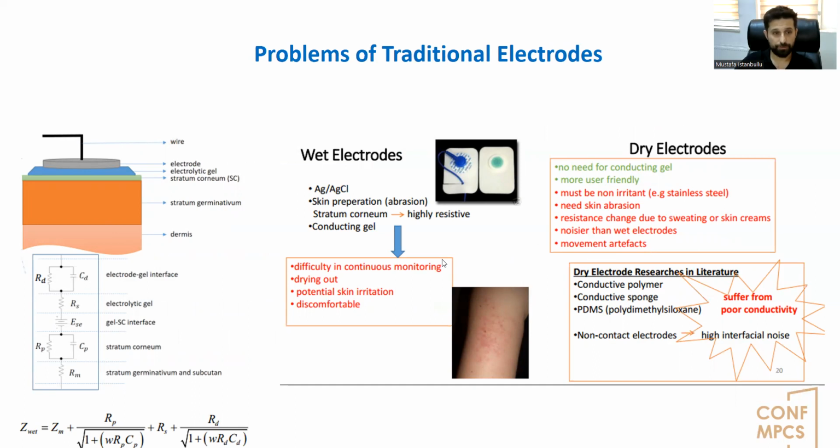In addition to the electrophysiological signals, there are also undesired signals due to noise, artifacts, and interference, occurring in the orders of microvolts or millivolts. Briefly, a biological potential must be noise-free to be clinically valuable. Since undesired signals mainly appear depending on the measuring electrode, the electrodes are crucial in terms of signal quality in a biological measurement system.